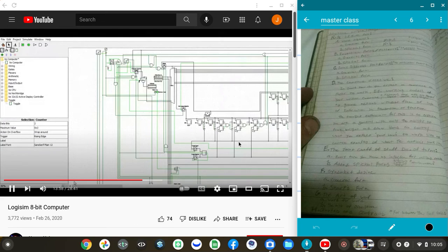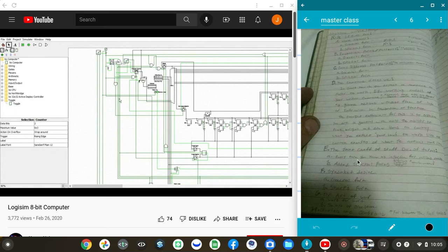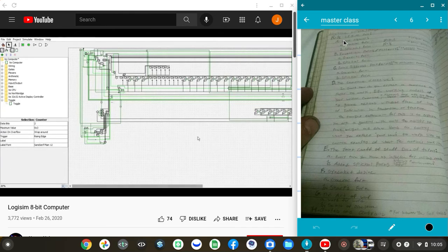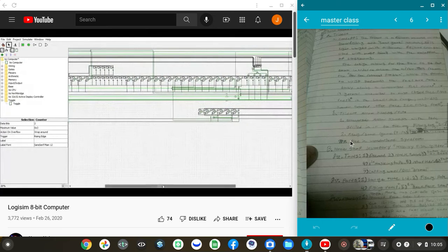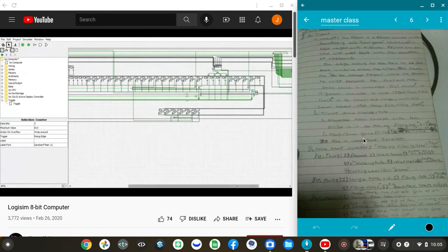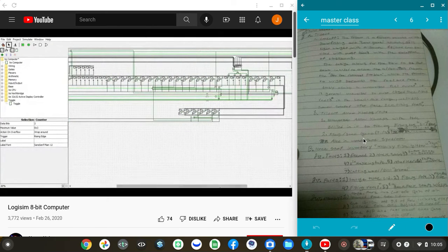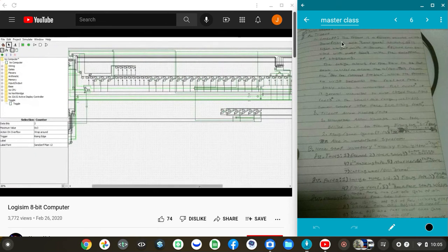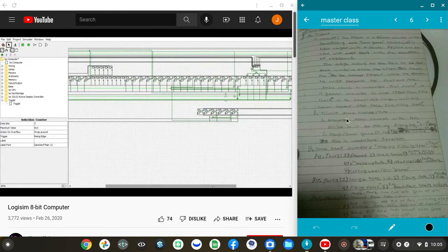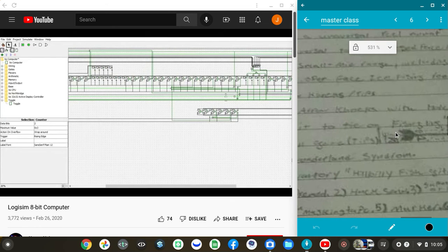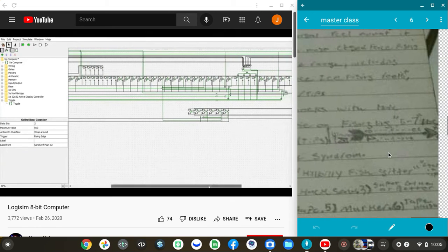And what's some other things that probably need pointed out? Oh yeah, I was in the middle of going through what chunk does what. We just finished with the little control chunk. Then we've got this whole line right here in the middle. This really long line, plus also this, and also this. That is the decode logic. That's what actually decodes the instructions and sets them up, or sets the CPU up for what those instructions are telling it to do.